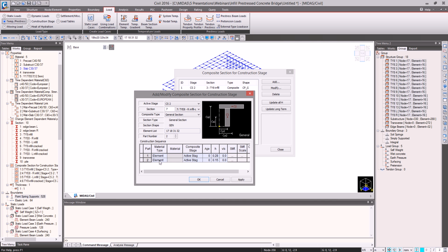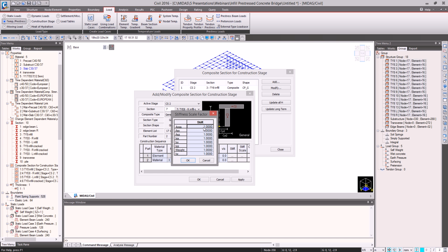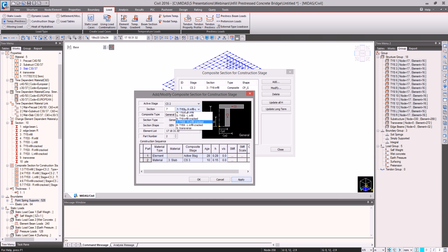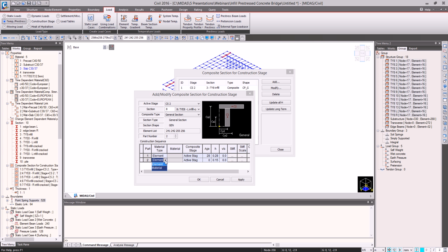and do the same for the other beams, for the other sections. Again, material, slab, stage 3, 10 days, and assign crack section properties. Using 0 means that I'm considering 0 contribution from the slab part for these elements.